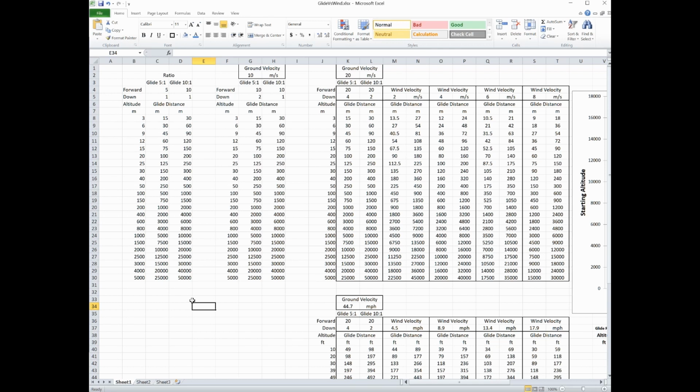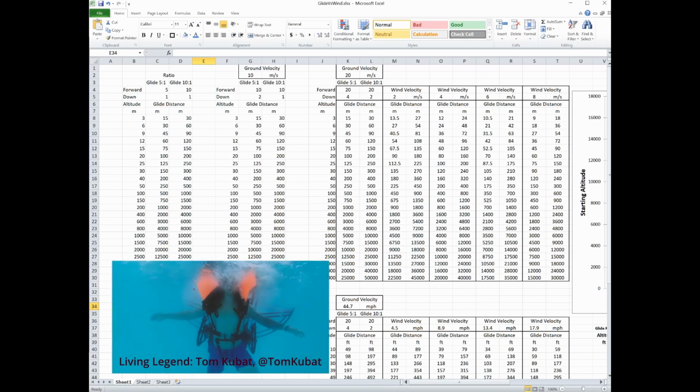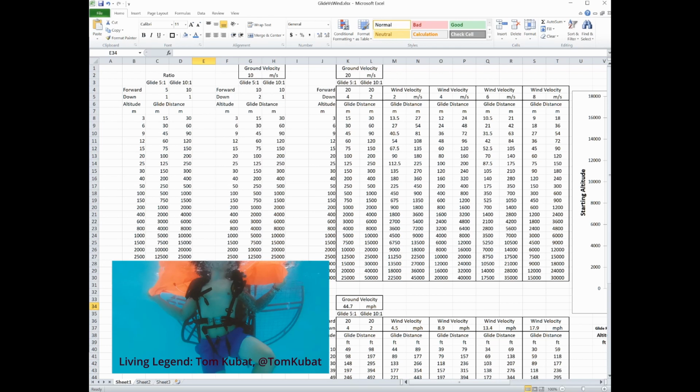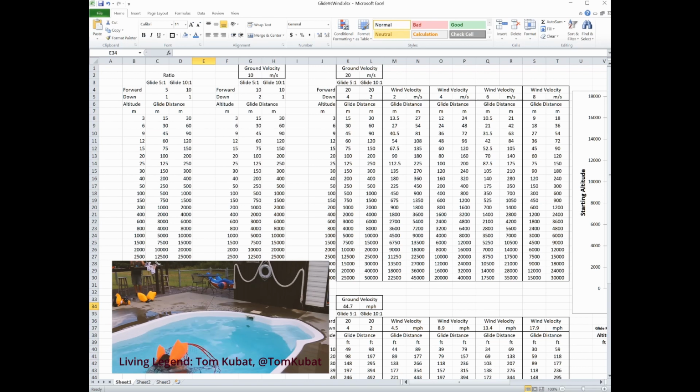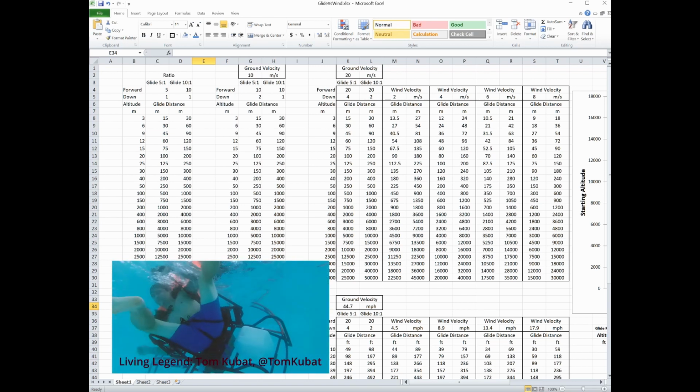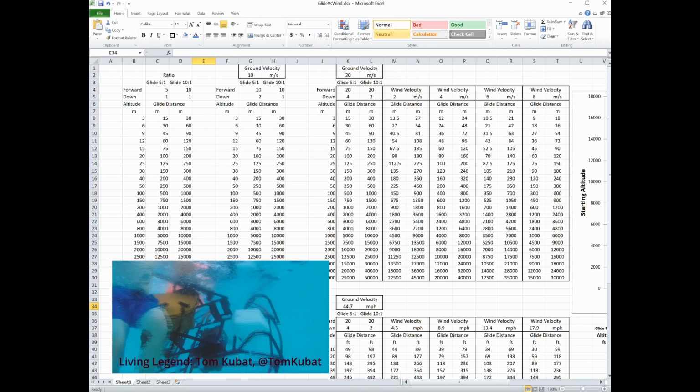If you're going to fly over open water, you need to consider your glide ratio and how wind is going to affect that, which would affect your planning to reduce your risk of dying, reduce your risk of ever touching the water. Because floats are a great thing to have, but it's not a magic bullet that is going to guarantee you're not going to end up at the bottom of the ocean or wherever, or the bottom of 4 feet of water. Well, that didn't work at all.